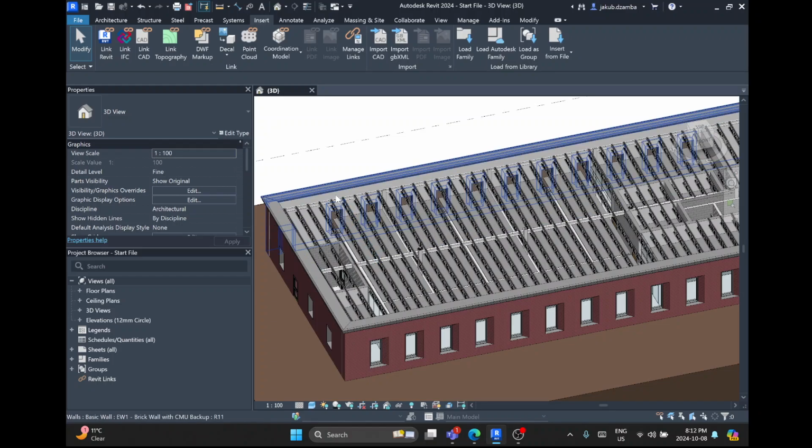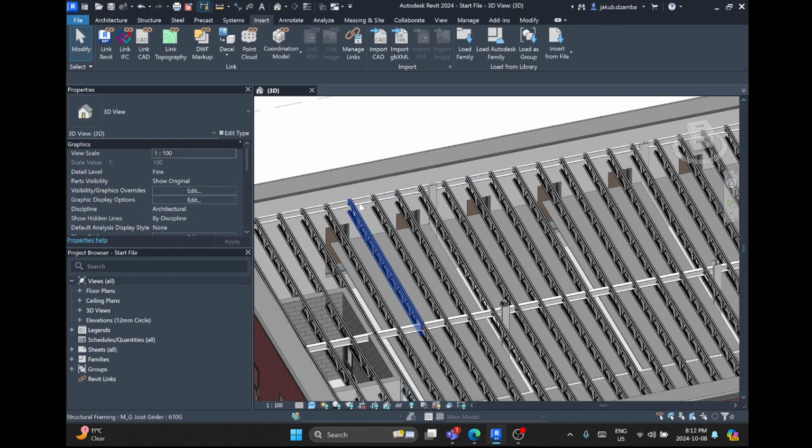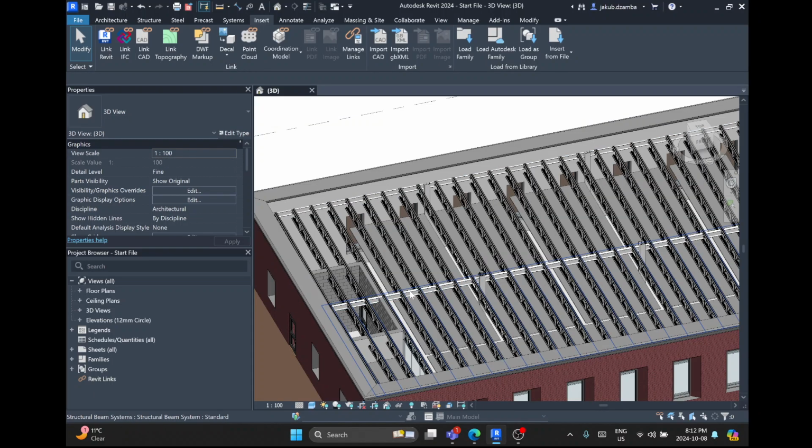But because it's structural, we don't need necessarily these beams to carry these joists anymore. We can just get rid of these beams and have the joists land right onto the concrete block. So all we really need is this central line of beams. So let's get started. Before we start deleting beams and stuff like that, I'd like to get to a structural drawing, which I don't have. I just have floor plans right now.